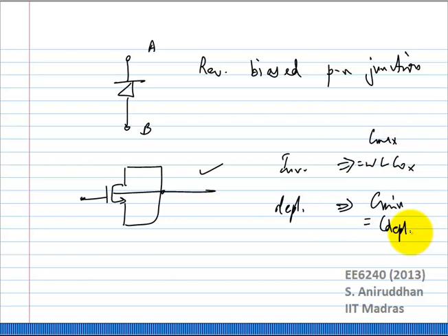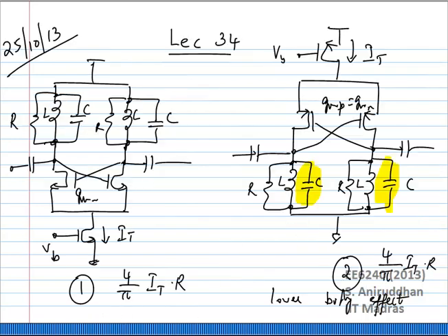Depending on the various parameters of the MOSFET, this ratio can be very large, anywhere from 2, 3 to maybe 10 or 11. It really depends on the parameters of the MOSFET. But the nice thing about it is it's possible to get voltage variable capacitors. What do we do next? We take this capacitor and stick it inside our oscillator. The simplest version, we are going to replace this capacitance C with that voltage variable capacitance.